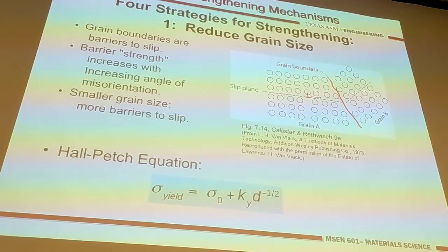If you talk to anybody in metallurgy, say in the materials department, okay, if you say dislocation is just a defect, it's not important, then you are basically not getting the point. Okay? So to strengthen metal, to enhance the yield strength and tensile strength, eventually you are dealing with the dislocation motion.